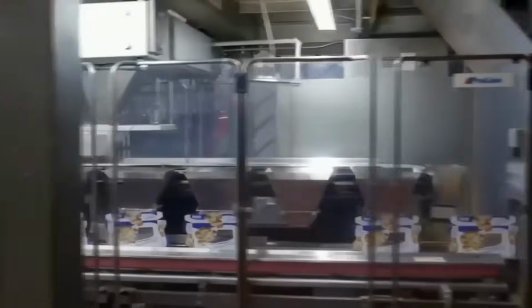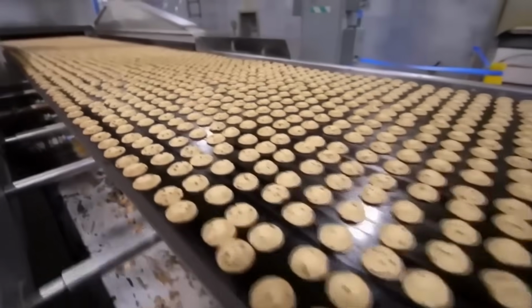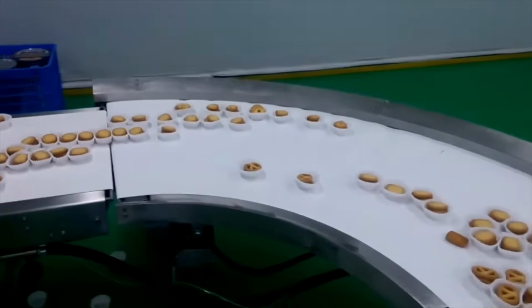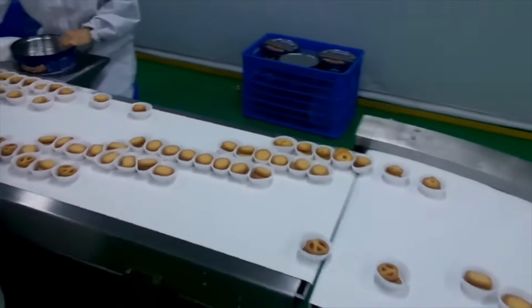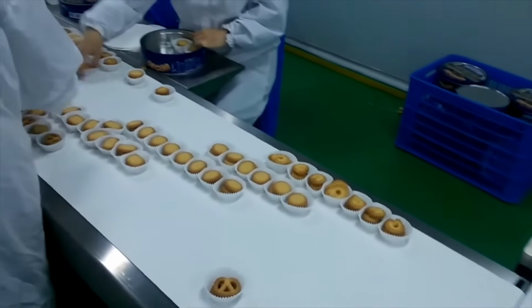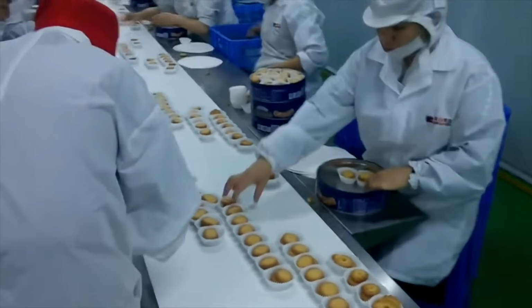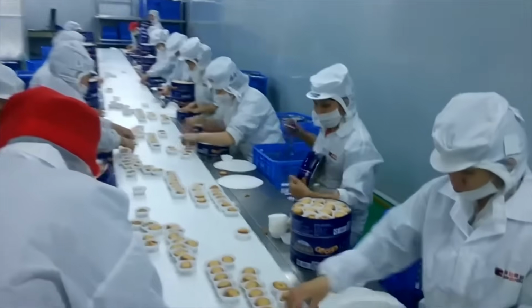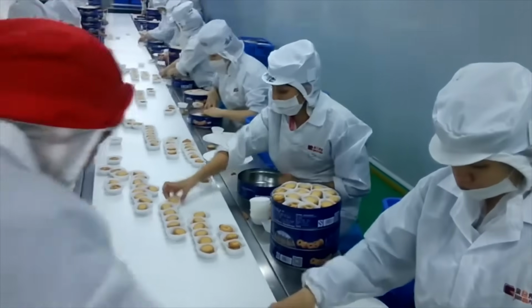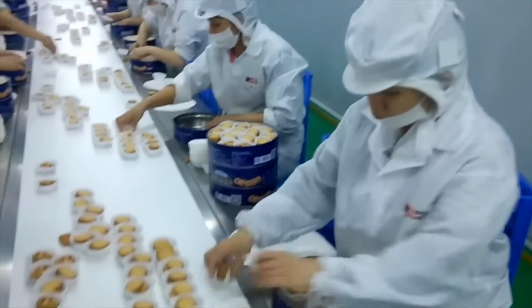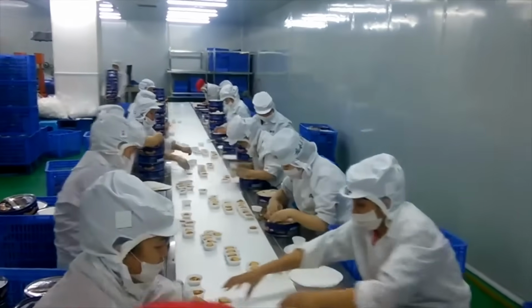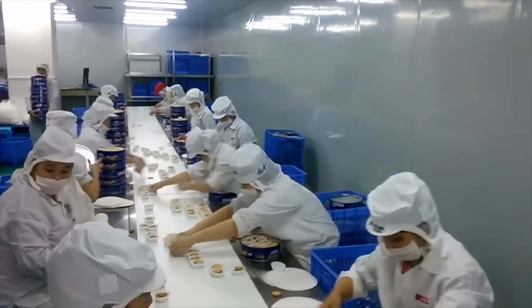If cookies are packed in trays, the trays protect against breakage. Cookies are loaded into plastic trays by robotic pick and place or by lane collators. Trays are then wrapped in film. Trays also control headspace and reduce movement that generates crumbs. For bagged formats, cookies are collated into stacks and then dropped into bags. Stack height and alignment are controlled so the bag seals cleanly.